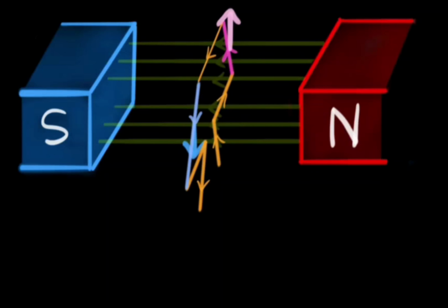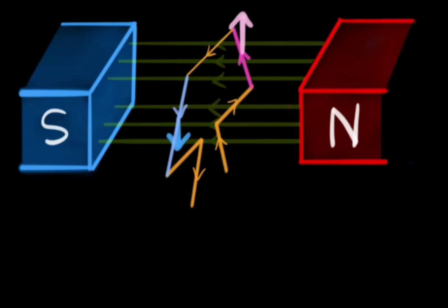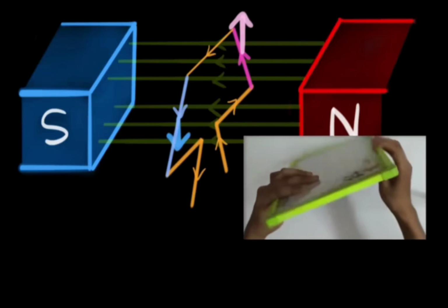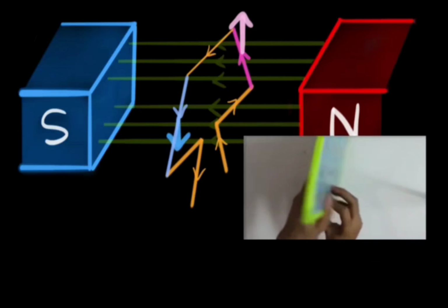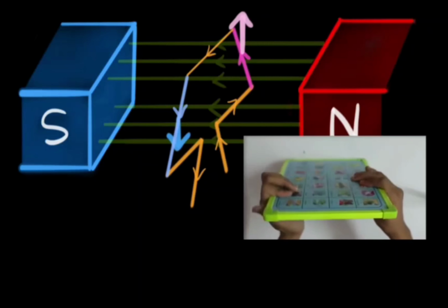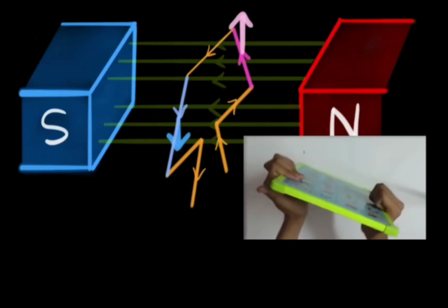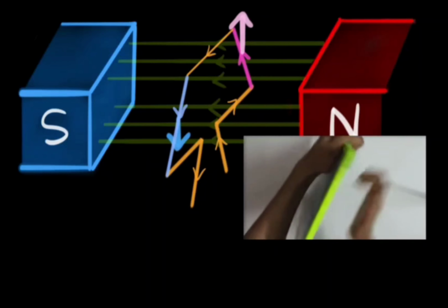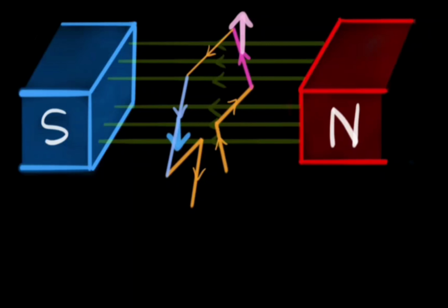So virtually no rotating torque acts on the armature at this particular instant, but still the armature does not come to a standstill. This is because the operation of the DC motor has been energized in such a way that the inertia of the motion at this particular point is just enough to overcome this null torque point. Once the rotor crosses over this position, the angle between the actual position of the armature and the initial plane again increases and the torque starts acting on it.